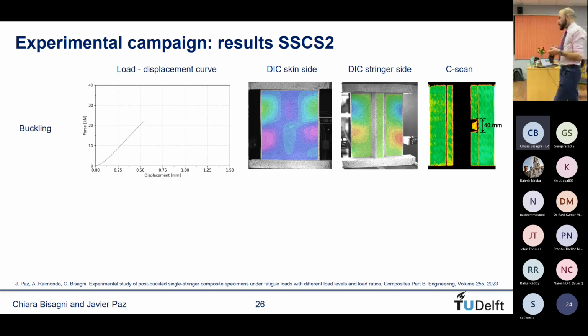The C-scan that we're using works in a water bath. Since the omega is constrained with the resin tabs, no water can get in, so we just see a black signal because it doesn't propagate. But here is the location of the initial teflon, and we see that it's still at 40 millimeters.